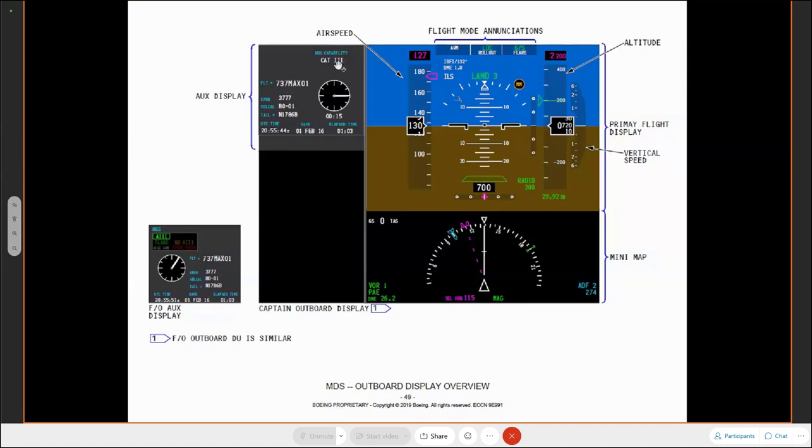On a lot of aircraft that I've worked on in the past, it will give you the capability of the autopilot, or in this case, the head-up guidance system, Cat 3, Cat 2, Cat 1, or if it's not available, US. Normally on aircraft, that is a placard, a sticker that you can change depending on the current capability of that system.